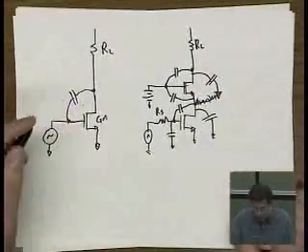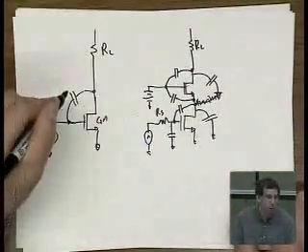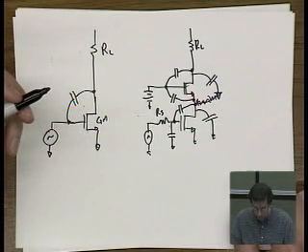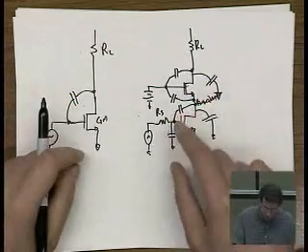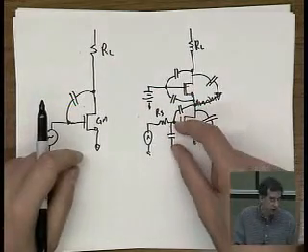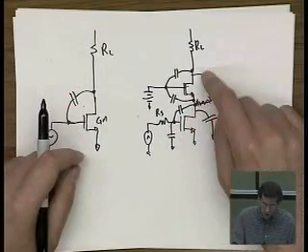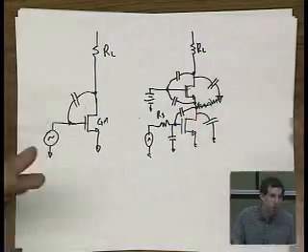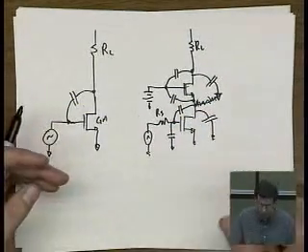So okay, let's look at this. Now the question is, now we have 3 nodes, right? So there are probably 3 poles. And if you use the analysis that I had said before, the voltage across this capacitor can be set independently. This voltage can also be set independently, but we have a new node. This voltage can also be set independently. So because there are 3 capacitor nodes that can be set independently, that means there are 3 poles. Okay?